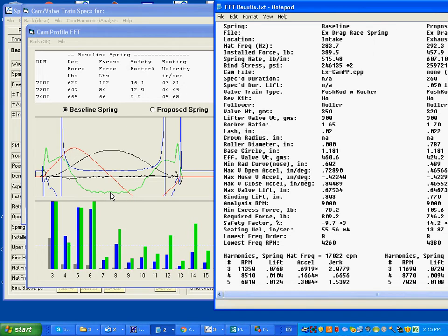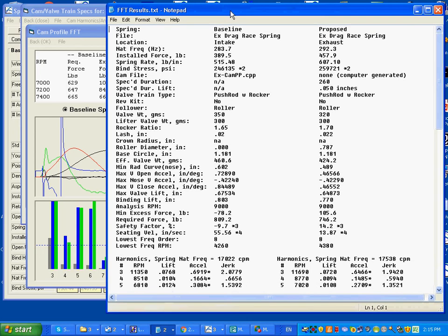How much spring force is required to keep the amount of mass that we talked about, that we showed you, at 9,000 RPM? How much spring force does it keep that to stay in contact over the nose of the cam? If you don't have enough spring force, it's going to launch off the nose and probably toss up here and then probably smack down over here. And our Engine Analyzer Pro does a nice job of illustrating and going through this also.